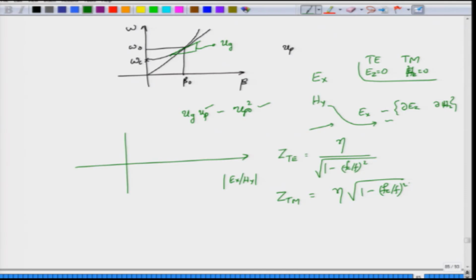So, if you are looking at a particular mode that you are interested in, what you can see is that at F equal to Fc, of course before F equal to Fc there is no concept of an equivalent impedance because there is nothing really happening, but at F equal to Fc, the denominator will be 0 and the impedance ZTE will be infinity.